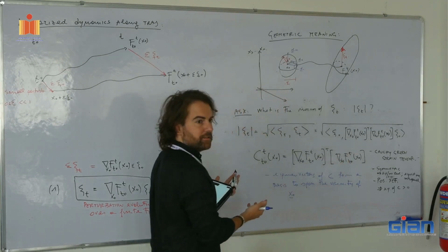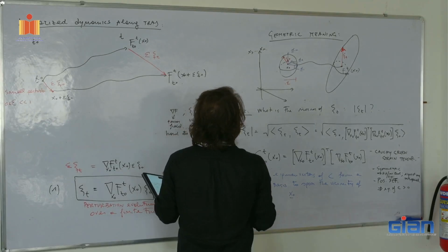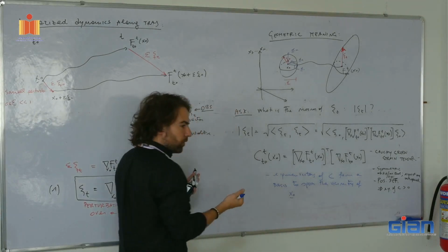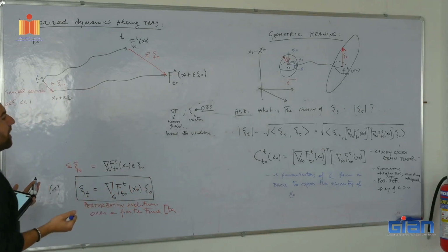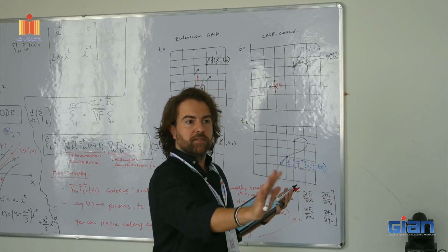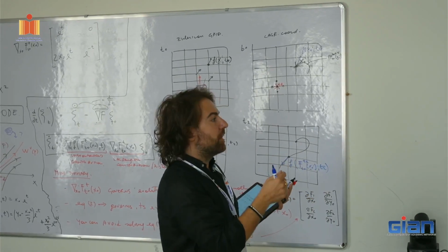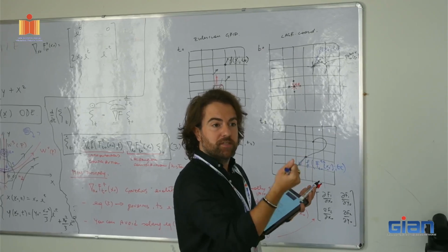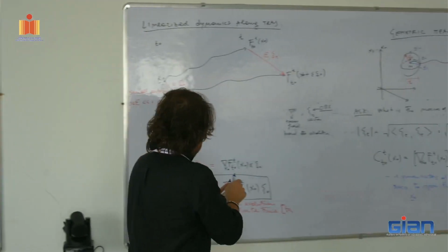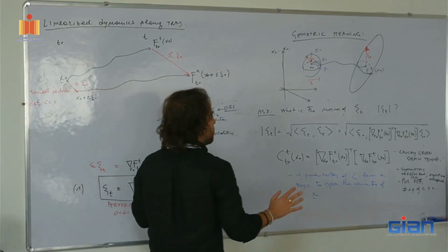get another matrix, okay? Why this comes naturally into place is because if you really want to understand strain, df is not the ideal quantity because df also accounts for rotations, right? So this guy factors out the effect of rotation and is just going to retain the information about stretching to some extent.